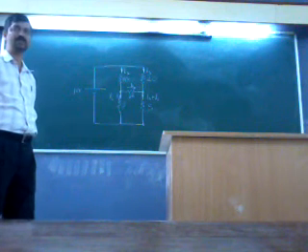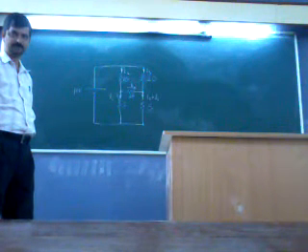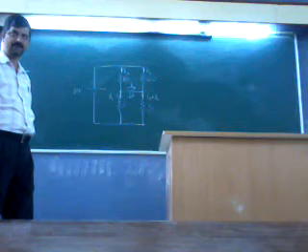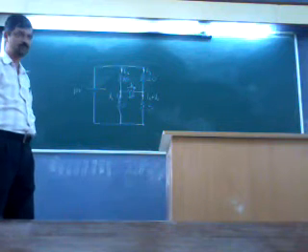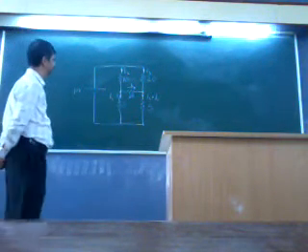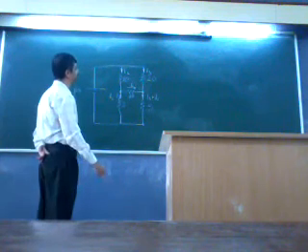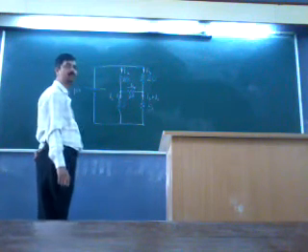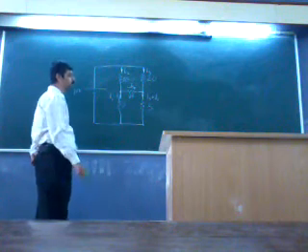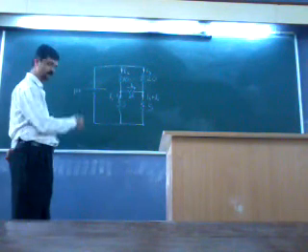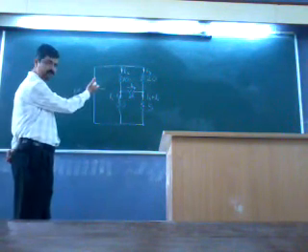Now Kirchhoff's mesh law is to be applied. There are many loops now which you can work, but better to take the loop in which we have voltage source. If we do not have voltage source in a particular loop, what is to be done we shall see, because a need has arisen for that also.